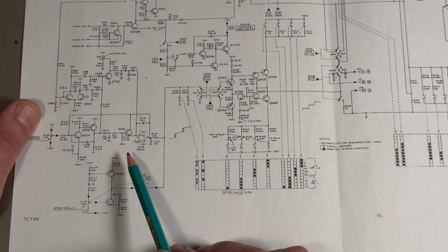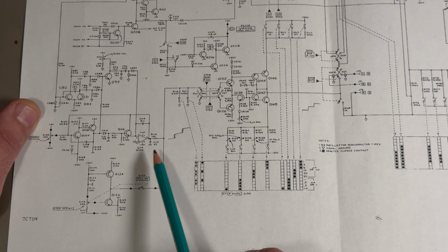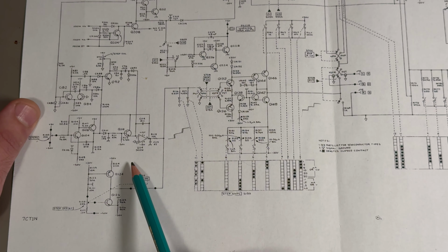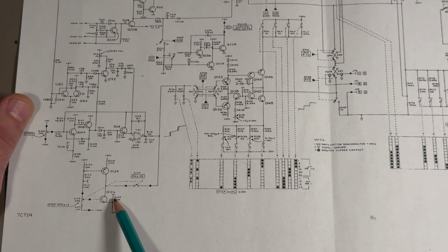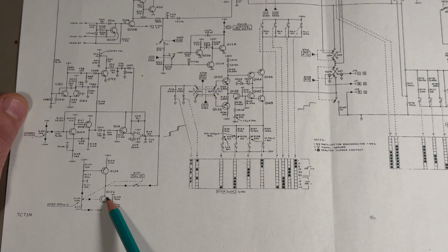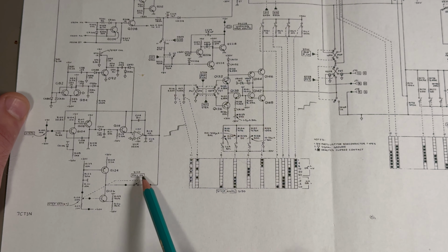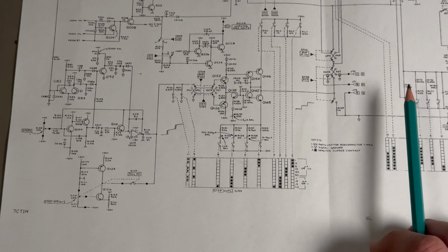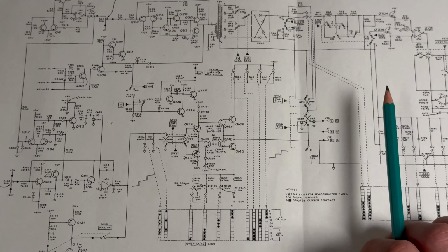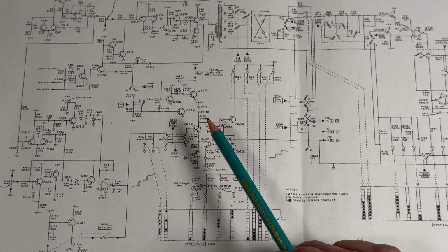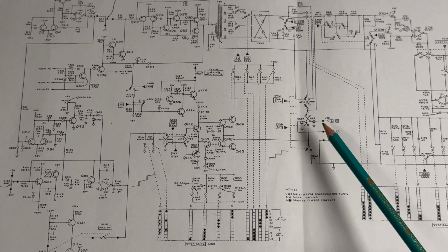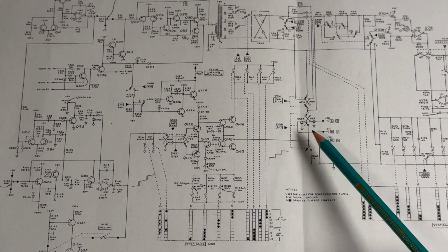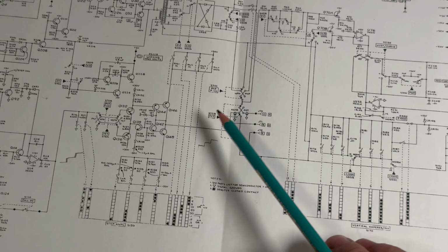Apart from that, you can have a constant voltage offset that you apply to the step generator, and this is very simple. It's just a voltage source. It's made out of 2 transistors, and it's enabled by this pull switch. And yeah, this is just a brilliant schematic. You can also have current fed into a base of a bipolar, or just voltage fed if you're looking at a JFET or a MOSFET or something like that.